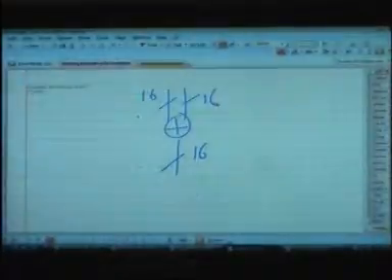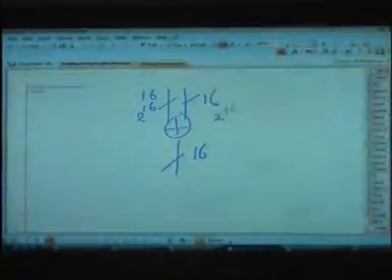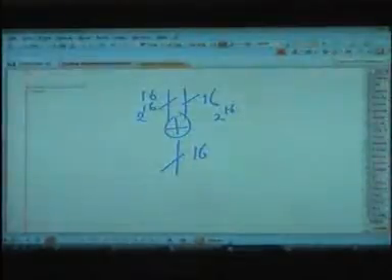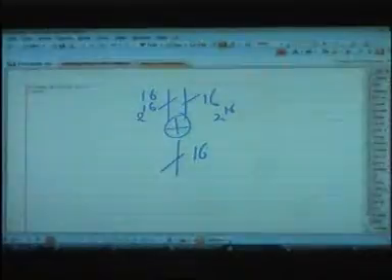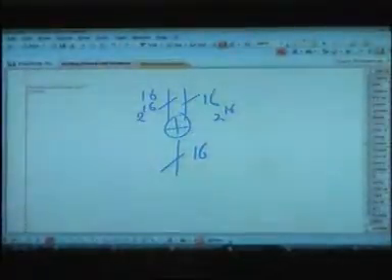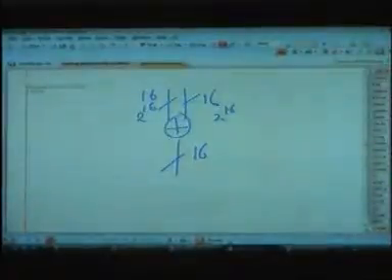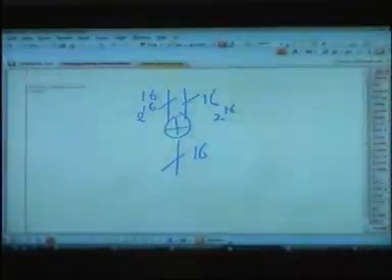Working means there are 2 raised to the power 16 possible values here and 2 raised to the power 16 possible values there. This is what is meant by working. So 2^16 into 2^16, if you give these many inputs and then you come and tell me it's working, then I'll believe it is working, because now I know it is really working, because you have tested it for all the possible values.